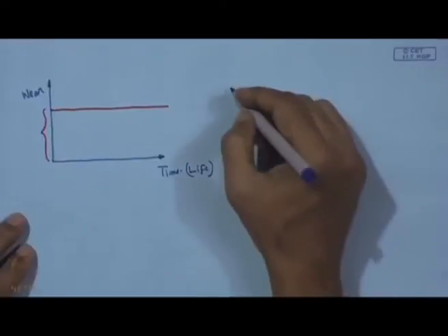When it is the bush bearing and the journal, that is the portion of the shaft which is inside that bush and which is rotating, if there is wear and if it exceeds a certain limit, and that limit is set by the operational requirement, and that is actually specified by the designer of that component, considering the safe operation of those parts.